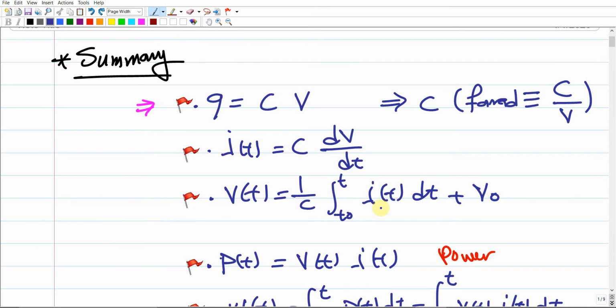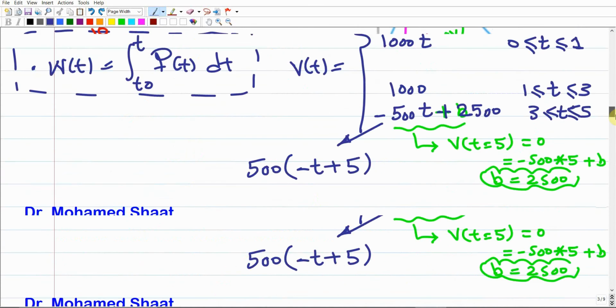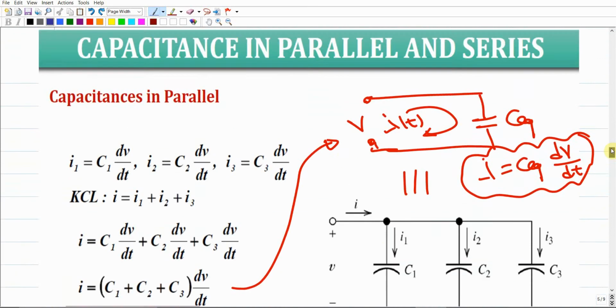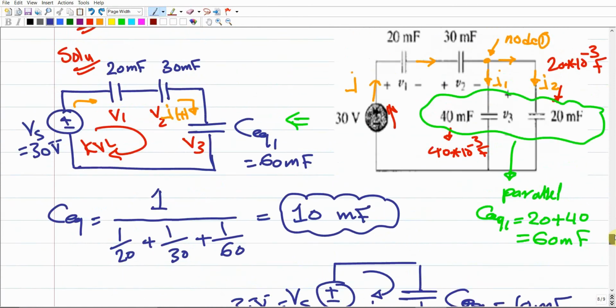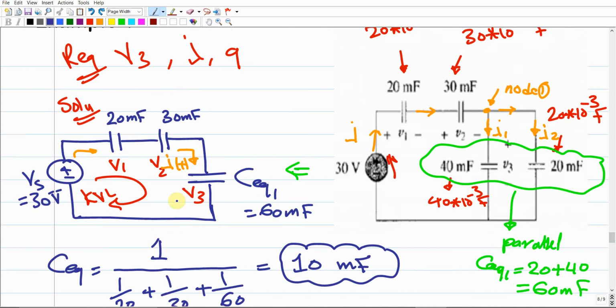In the equation down there, the current was 0. And even the integration of the current gave us the charge. So both are kind of the same functions, right? So it is easier for us to find the volt as Q over C. So if I ask you, generally, how much is V3 for this electrical circuit? It should be Q, which is the charge over this capacitor, divided by the C of this capacitor. So how much is the charge here?